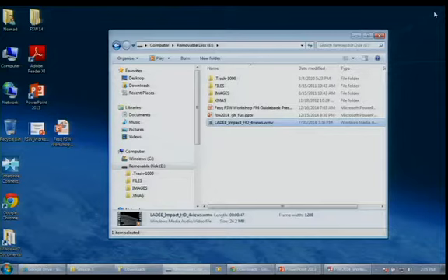I'll refer you to my last two flight software talks, but we had a unit test suite, we had integrated test suites, we had scenarios of all the major phases of flight, we had scenarios for all of our fault management activities, and these all got run. And the data was put into a very large database, and then we had a script that would post-process all of this data to look for violations of our requirements.